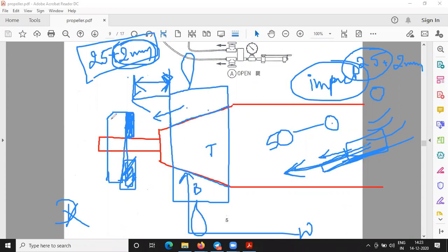Sir, the cushion is kept for this propeller nut also for removal. Yes, sir. See, why this cushion? Because this should not come and damage this. After the cushion is there, once this boss comes to a halt, remove the cushion. At that time you can rotate the nut very easily. The nut has got holes on it, like the pin you take to rotate the hydraulic nut. Similarly, you have a big rod which you insert in this and rotate, just like how you turn the generator engine using a rod on its flywheel. Same thing you can do here.